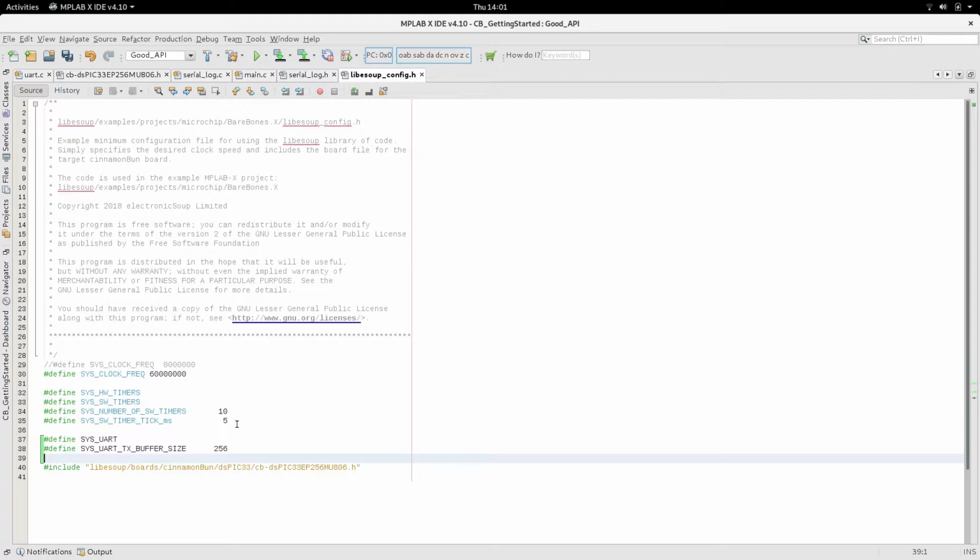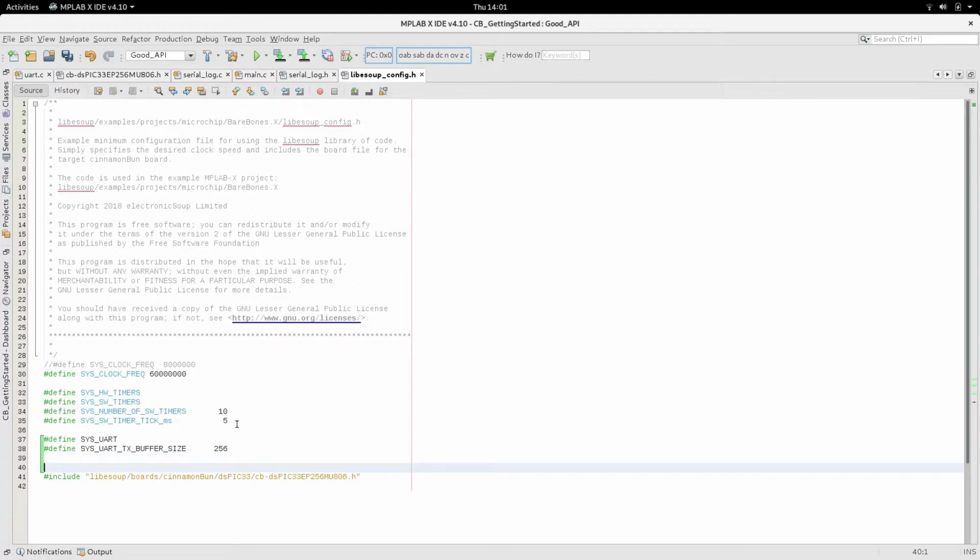I think it's probably better to have that as a configurable item in the configuration that you're sending down to the serial port API, and say that I want a serial port and I want this size of a buffer. One of the problems with that is that it's dynamic, and then you're taking memory out of a heap, whereas if you've hard coded it before in this mechanism, the buffer size is defined at compile time, so there's nothing coming off a heap. But yeah, I'll figure it out, and I may refactor it.